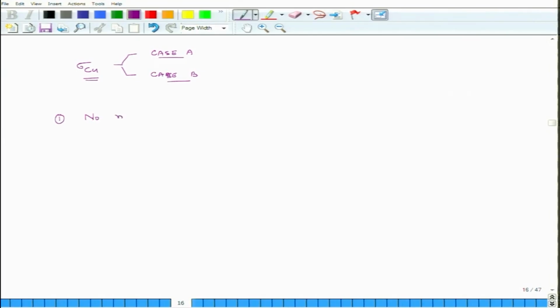We assumed no misorientation of fibers. So, we assumed that all the fibers were exactly straight, but in reality the fibers may be at some direction, they may be more or less in the 0 degree direction, but not necessarily perfectly aligned with the 0 degree direction.